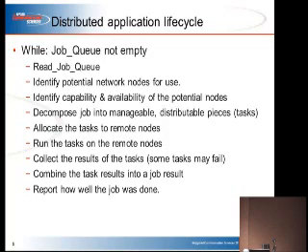The task could be, for example, I want to scan the spectrum between 400 meg and 2 gig, but maybe the entities themselves are not capable of doing that whole scanning job, so you have to break it into pieces, and each individual node might be scanning a sub-portion of that spectrum, or a sub-portion in a specific region. That's a very simple example of how you would break down a job into individual tasks and allocate those tasks to individual nodes.